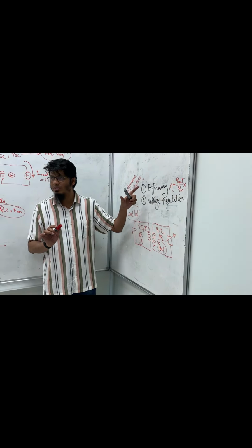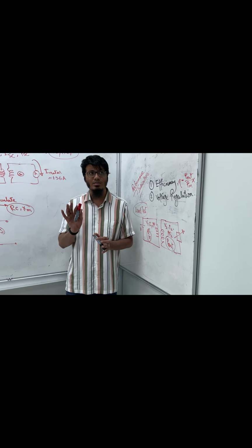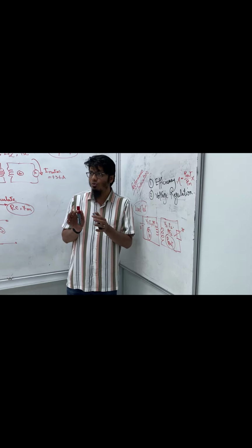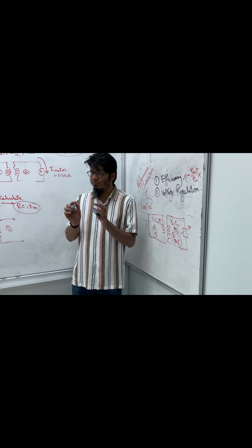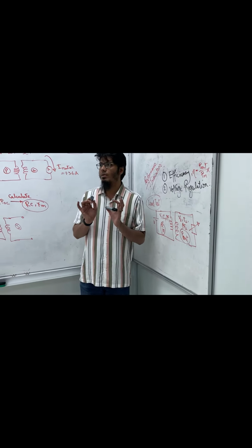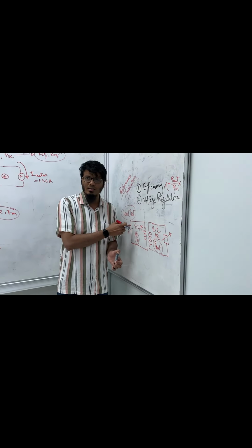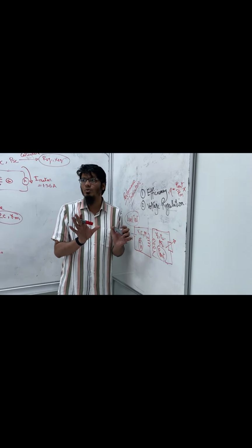Efficiency, you understand? Now in the exam, some part of the exam will be viva, interview. You understand? And I will ask you this type of question: if you want to find out the efficiency of the single phase transformer, how will you do it in the lab? You have to tell this. I will connect a load in the secondary, then I will apply a voltage, I will measure this, I will measure this, and this formula we will use to find it.